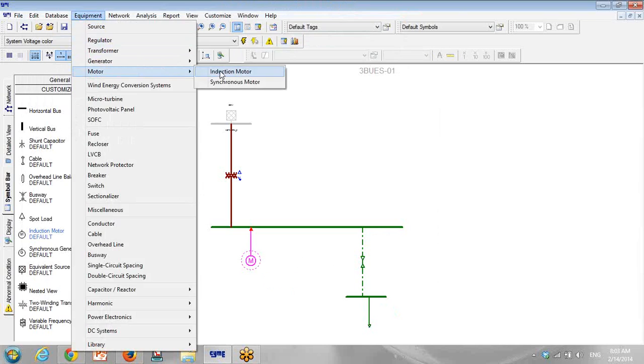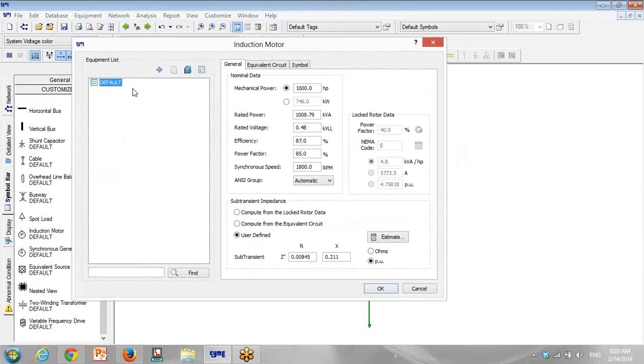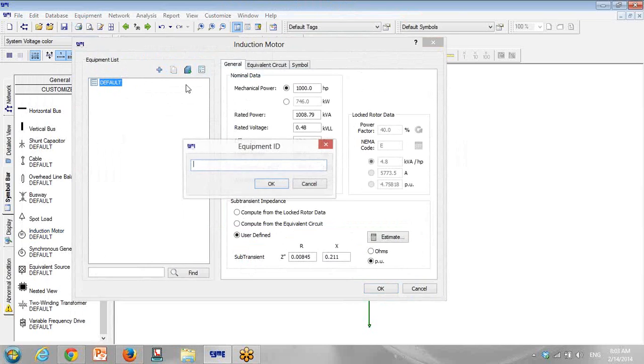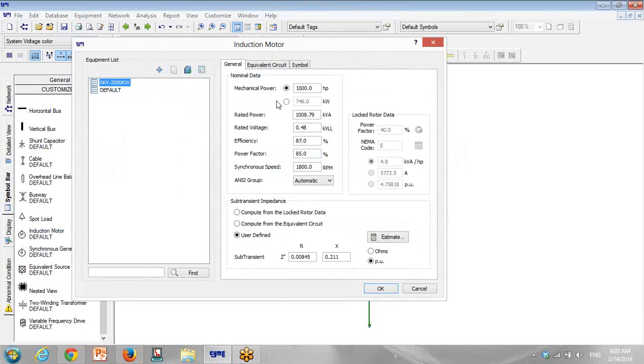again, let me check it. Oh my God. Okay, I create it again. I click on cancel. So it will be a motor 6 kilovolt, 2000 kilowatt. Again, I have to calculate it from 0, 2000. Then efficiency 93, voltage 6, and power factor 91, speed 1500.